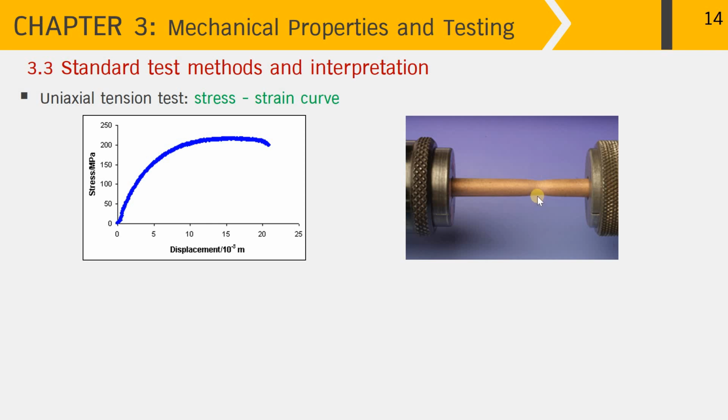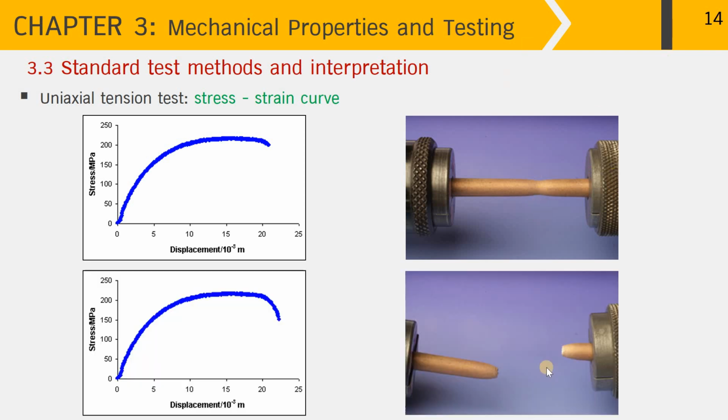It is not necessary that necking will take place exactly at the middle of the gauge length. It can take place anywhere along the gauge length. Once it happens, the deformation is not uniform anymore, and this reduced section will lead to the final fracture exactly where the specimen necks. And so we have fracture, as you can see on the stress and displacement curve as well.